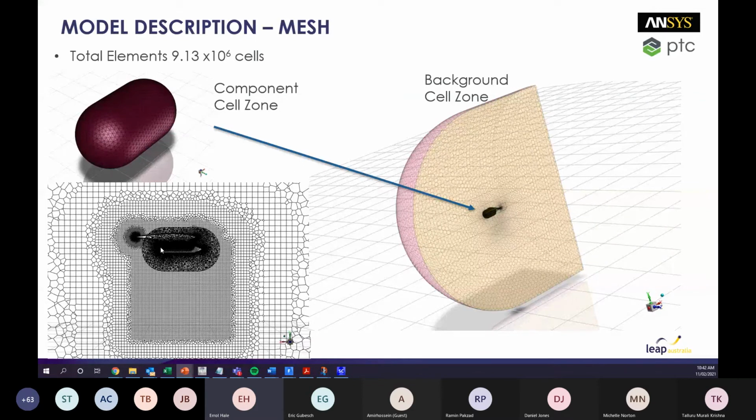Okay, and now you have your flow coming in at some velocity, so it comes through all of these elements. For those of you who are interested, yesterday we were talking about having a buffer layer between our polyhex core. That's what that looks like. To avoid the 1 to 8 octree transition, we've got some size of hex core, our polyhedral buffer layer, and then more hex core. So to avoid that transition, that's what that is there.